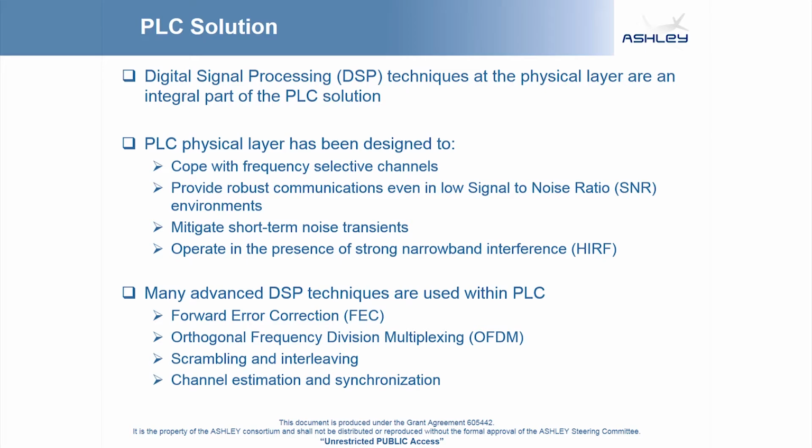Also, channel estimation and synchronization allow the receiver to synchronize to the signal from the transmitter, even though they both have asynchronous clocks. It is these techniques, among others, that provide for reliable communications, even in the harsh environment provided by the aircraft power distribution network.